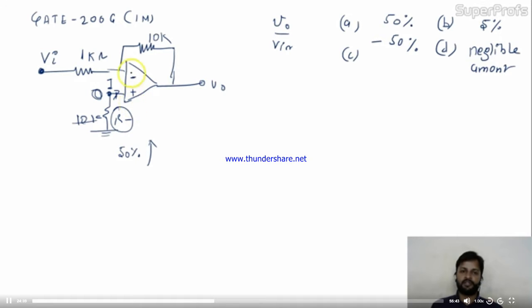Op-amp, see, this is the op-amp. Op-amp does not take any current from the circuit. So current is 0, no voltage drop. Whatever the value of resistance will be at the positive terminal, at every time, whether it's R or 2R, 3R, the voltage will be 0. The same voltage will go over here.